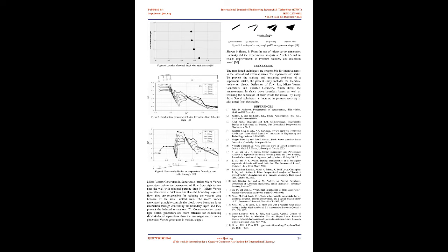But S. Das and J.K. Prasad did an experimental and computational investigation on cowl bending with bleed. Providing the bleed, the bleed mass flow ratio decreased, but an improvement was noted in the performance of an intake, as shown in Figure 5. At starting conditions, shocks are attached to the cowl tip. The reflected shock attaches to the ramp surface boundary layer, which creates some unsteady conditions in flow and a reduction in performance inside the intake.